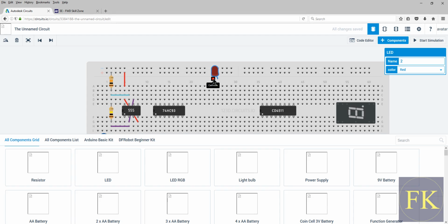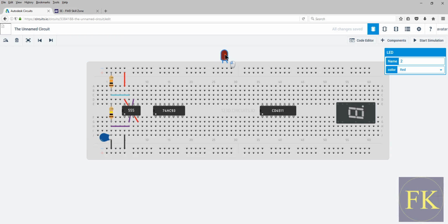This short side is the cathode, so you have to connect this to negative, and this anode is positive, or usually the output of the IC, because you're going to be using the output of this 7493. So I'm going to push it somewhere here because my ground line is here. I'm going to connect ground like this.